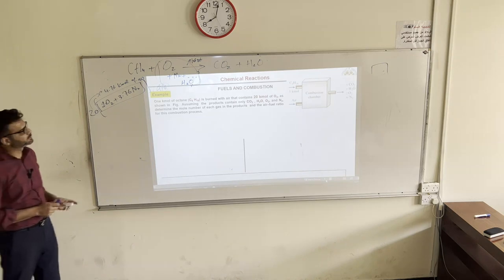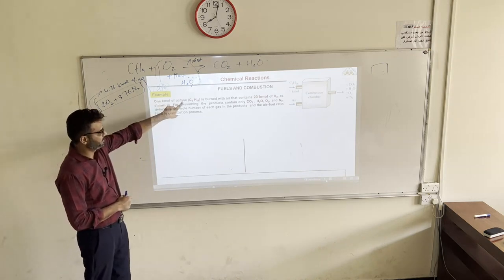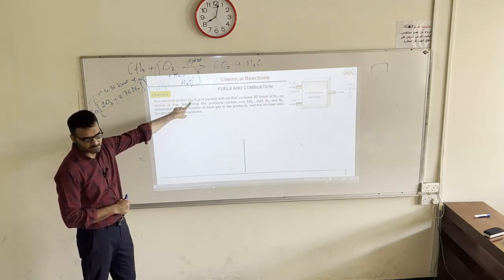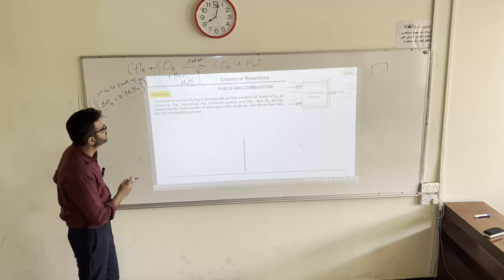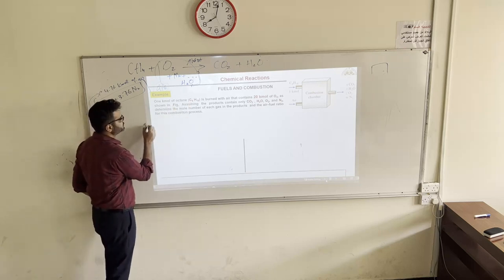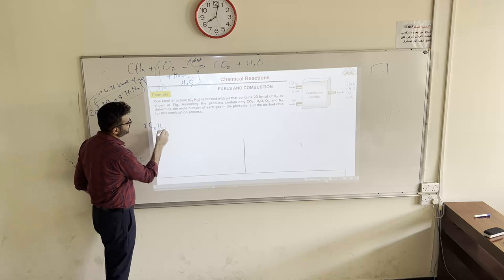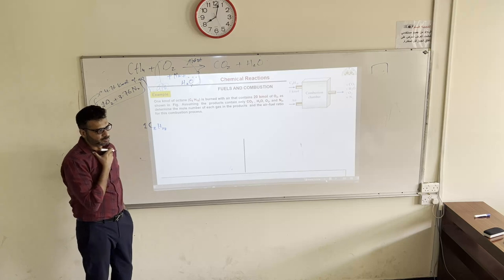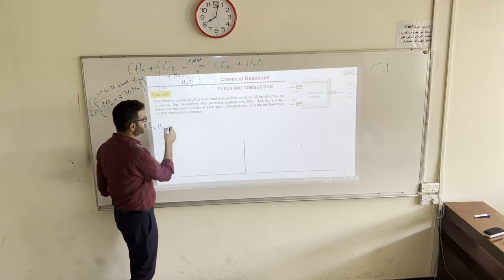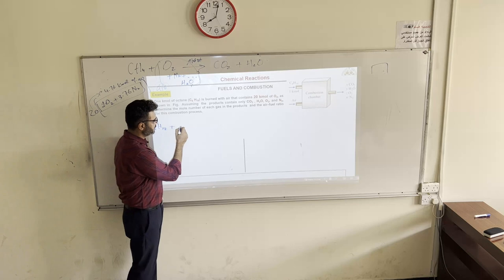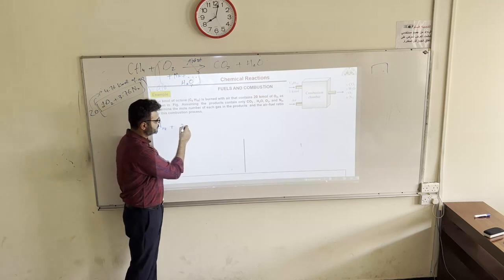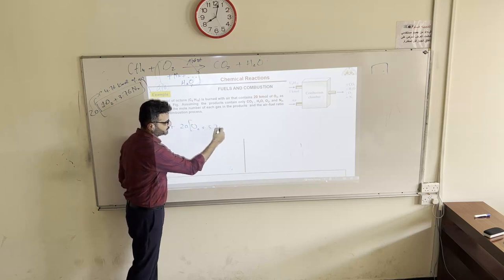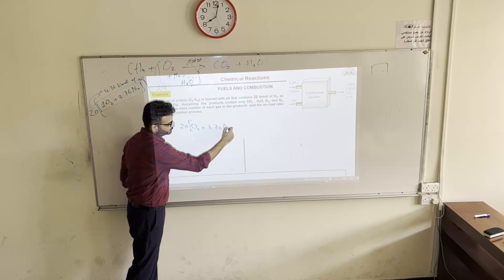Let's solve one question. Now here we have 1 kilomole of octane, that is petrol, gasoline. So 1 kilomole of C8H18 is burnt with air that contains 20 kilomoles of O2. So it reacts with air, in which we need 20 kilomoles of O2, which means with 1 kilomole of O2 there will be 3.76 kilomoles of nitrogen.